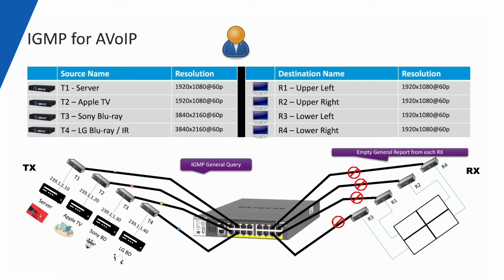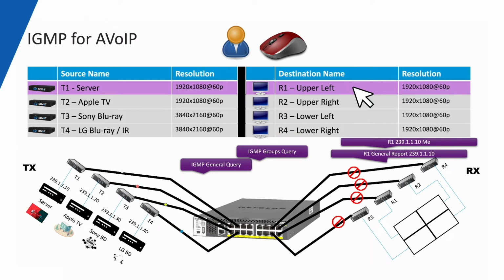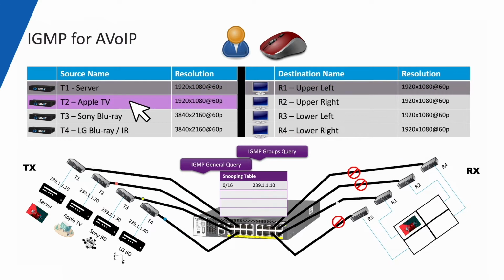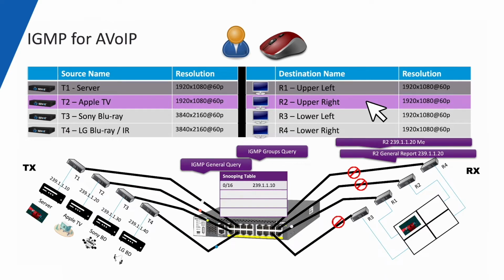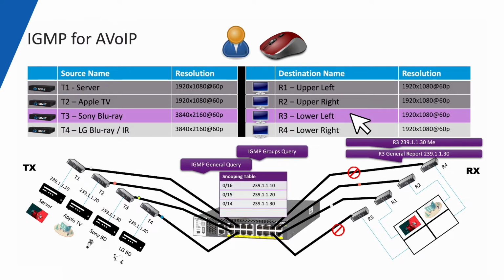How does it work exactly? Take this installation. That's a single switch, very easy, right? In that single switch installation, you have four encoders on the left. Each encoder is attached to an audio-video source. And you have four receivers on the right-hand side. With your SDVoE installation, you have not only the endpoints, encoders and decoders, but you also have your controller. As soon as you connect those encoders and decoders to your network, the controller will discover those endpoints and classify them between sources and destinations. So the controller is controlling your video endpoints, encoders and decoders.